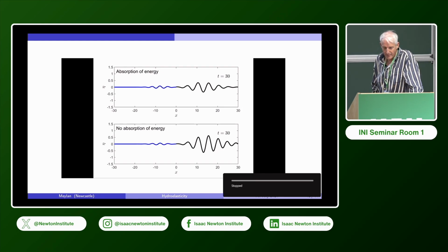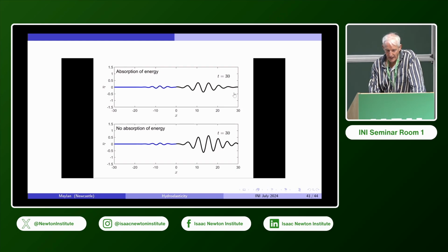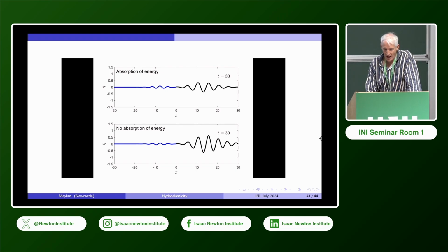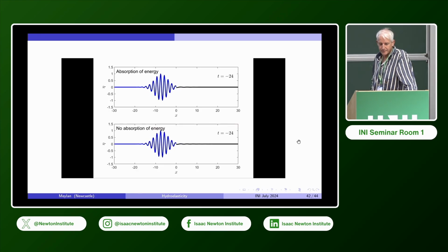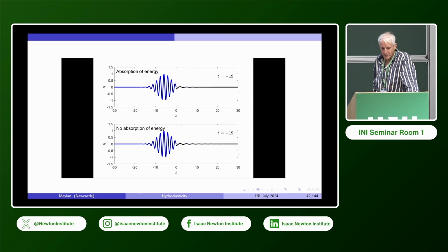You can see here that the pulse energy is getting absorbed more slowly because the bending is less. Of course, I haven't taken into account that I've just kept the imaginary part of this material the same. I haven't changed it as you would have to if it was a proper piezoelectric material, because it would favour certain frequencies over others. And then here's the solution for some very high frequency packet.